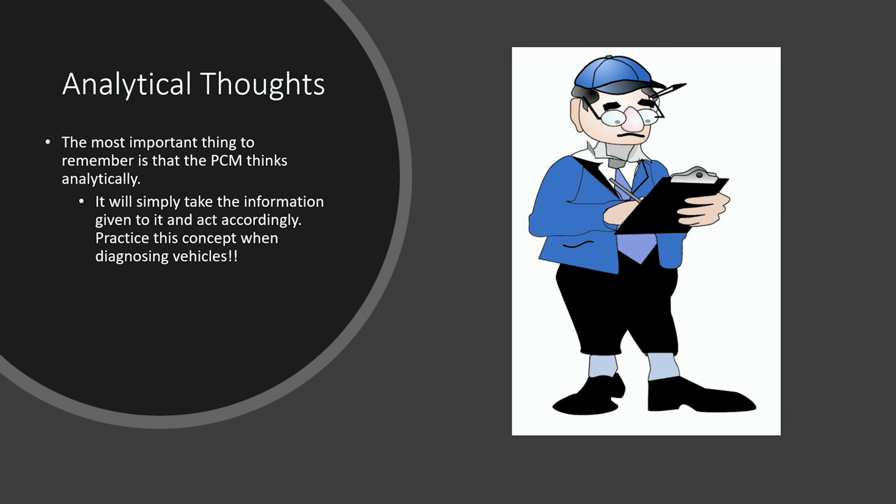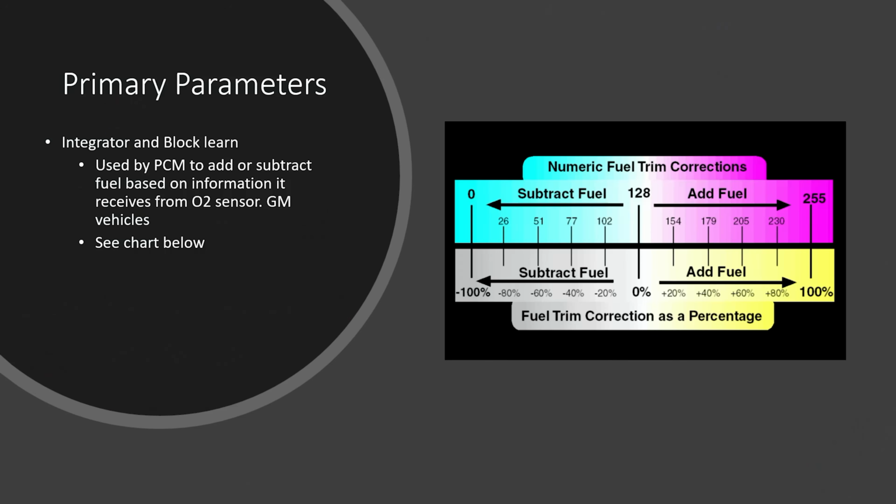The next thing I kind of want to pull up is always when you're approaching a diagnostic dilemma, whatever it happens to be, is to try to think the way how the computer is geared to operate. Then you have a much better shot at being able to diagnose a car. Now that's assuming that you had the proper training over the years and you understand how a computer is supposed to operate. So, going back to richening the mixture and leaning out the mixture, there's something that's called fuel trim. And we addressed this as one of my 6 main go-to PIDs in the earlier YouTube video.